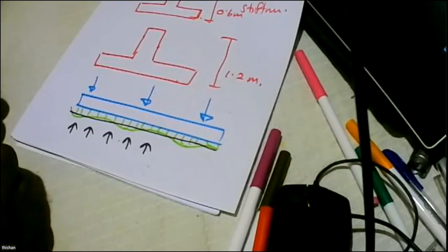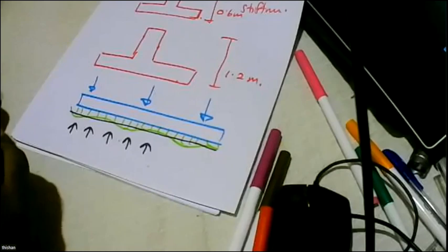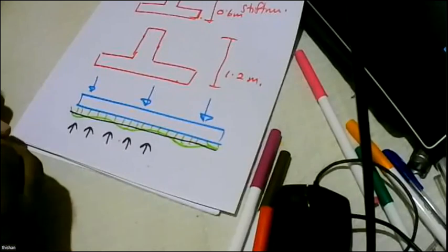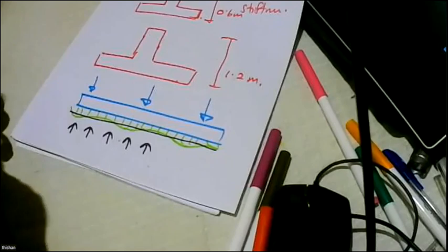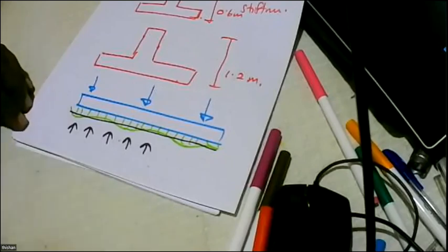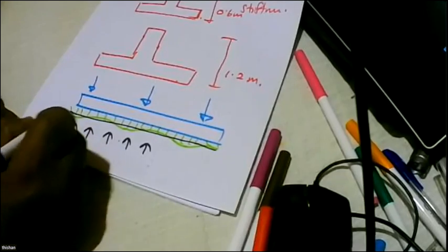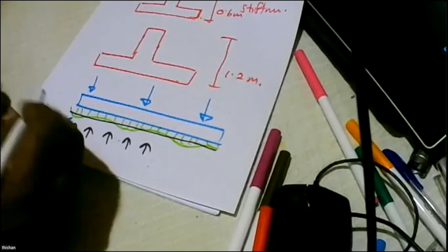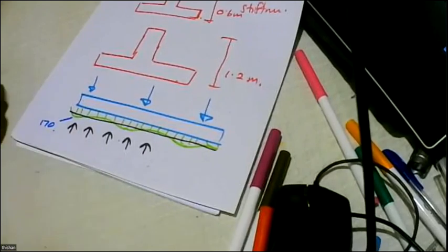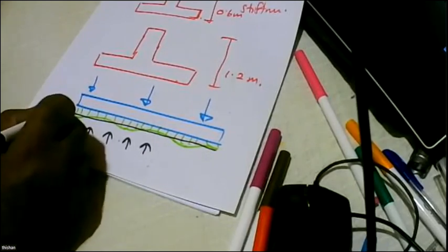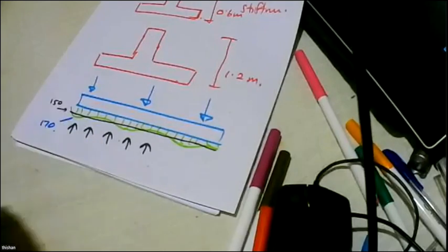And to experiment with different soil parameters, and also to see what kind of stresses occur, we can actually change the stiffness of the foundation easily by using Winkler springs. Because sometimes you might find here you might get 170, but when you increase the stiffness of the foundation, you might find it drops to about 100.